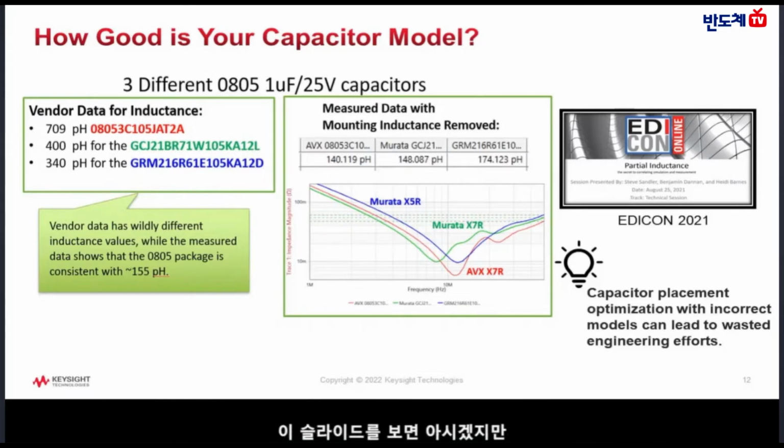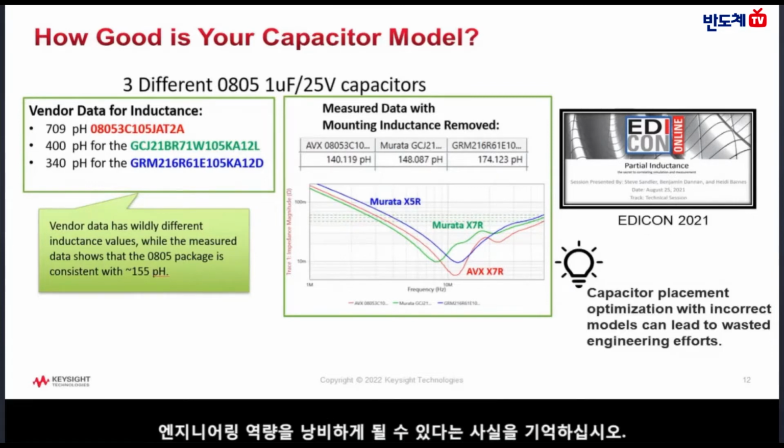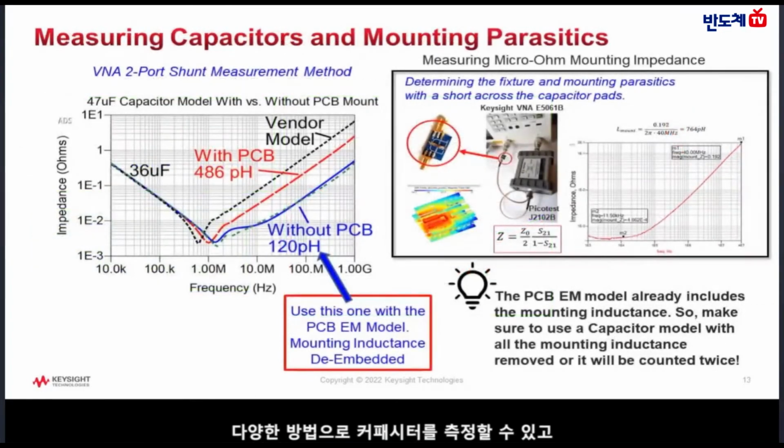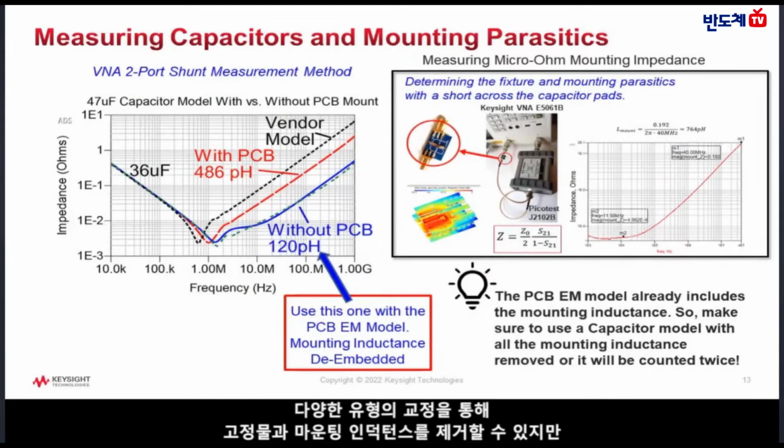I hope that this slide convinces you that all capacitor vendor models must be verified with measurement. Just remember that capacitor placement optimization with incorrect models can lead to wasted engineering efforts. There are different methods to measure capacitors and different types of calibrations to remove the fixturing and mounting inductance, but